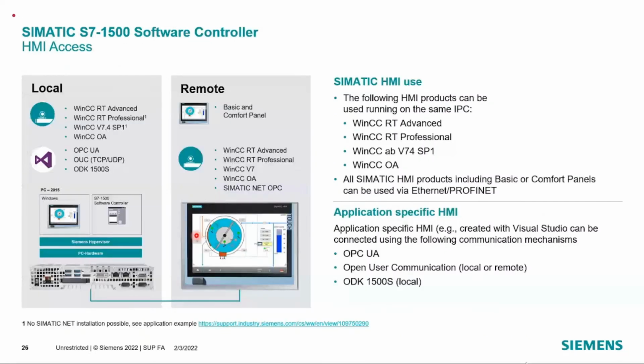And HMI connectivity: whatever I told you about is the controller functionality, which is very well known. But on the same controller, if you want to run the SCADA functionality, there is a possibility to connect even an external HMI. Apart from that, there is also the possibility to install the HMI runtime like WinCC Advanced, Professional, WinCC Classic 7.x, WinCC OA, even OPC UA. That is also possible to install on the same PC. So on the same PC, we'll have SCADA as well as PLC together, along with the Windows functionality.